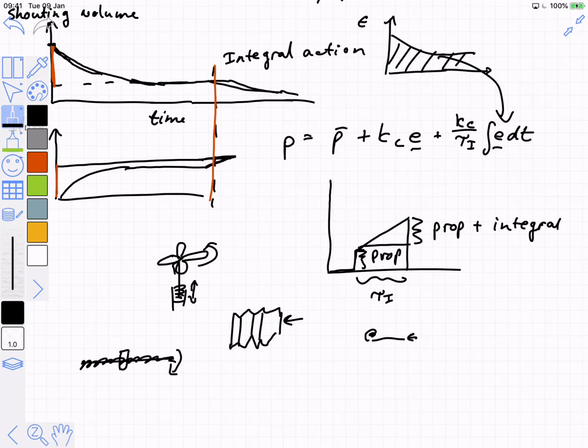If I blow in here, this position will show the integral of the amount of breath that I've blown into that whistle, right? And so this is how mechanical integrating devices were implemented. The reason why I'm off on this mechanical kick has everything to do with resetting the integral, and it has everything to do with understanding this other thing about the integral, which is that it can wind up.